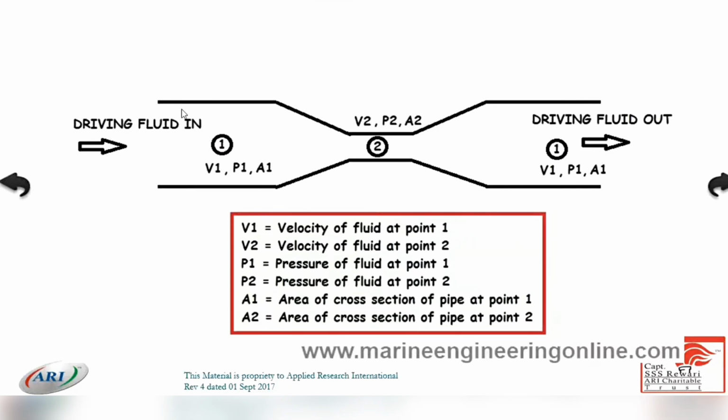The same thing is happening here. There is a flow of liquid here. Certain flow is there, and the same flow is here also. The same quantity has to pass through the smaller diameter line. When it passes from here, the velocity will increase so that the same quantity reaches here. So when there is an increase in speed, and if I put a pipe here and put a valve on that pipe and keep that valve shut, there is no flow of any liquid here. That means there is a high pressure here, there is a low pressure here.